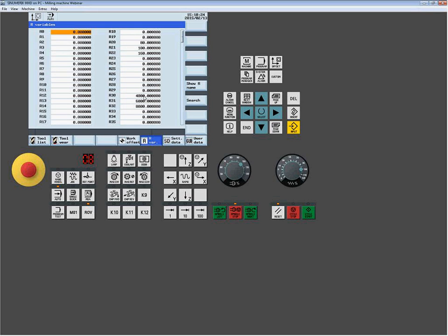Maybe you don't want operators going in and editing that in the part program. You can go to this column right in the offset table, and they can write them right here. But it's always going to utilize what's in the part program over what's sitting in this table. So it's only secondary if it doesn't get written anywhere else.